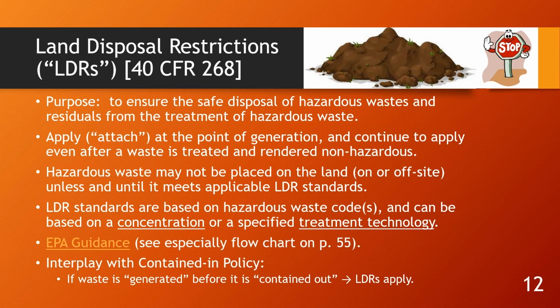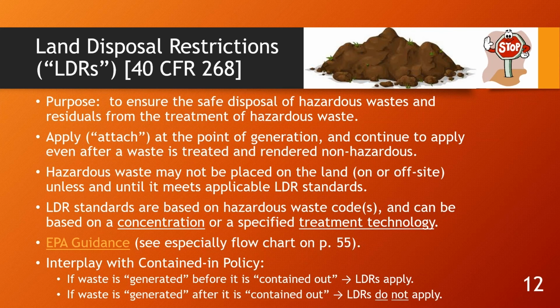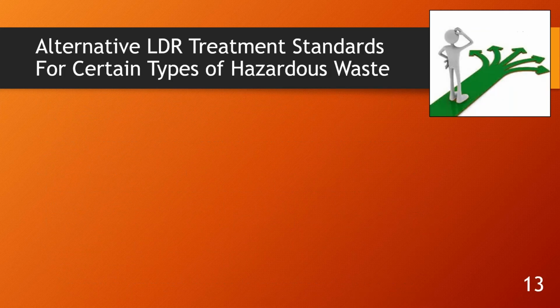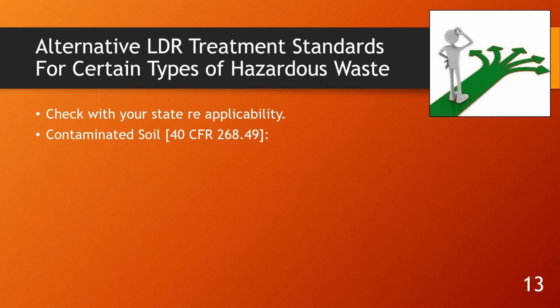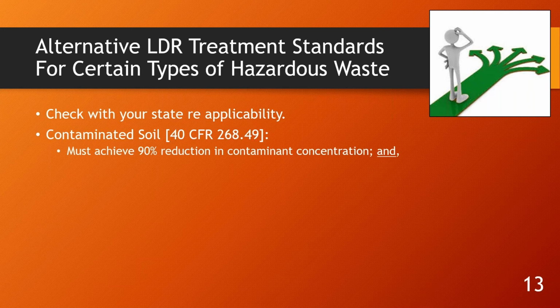And I mentioned before about the contained-in policy. If a waste is generated before it is contained out, the LDRs do apply. Okay, alternative treatment standards for certain kinds of waste. Contaminated soil is one of those wastes that has its own special treatment standard in 40 CFR, and it's 90% reduction in contaminant concentrations and cannot exceed 10 times the universal treatment standard. This is something that you'll find in RCRA. It's chemical specific.